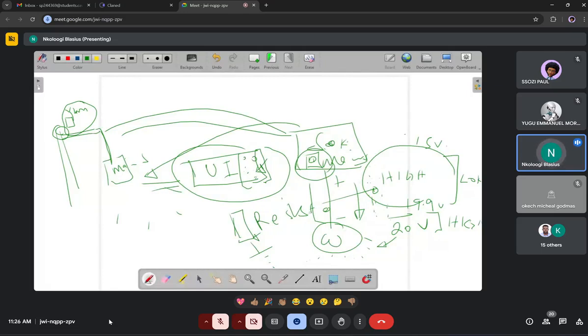But if you included the pull down resistor, it will set this range to default low or default zero. So you cannot see the situation that, even if you have switched off this bulb, it can try to blink. But also the other situation can be that the bulb is soon getting spoiled, so it can no longer feel the presence of the pull down resistors.